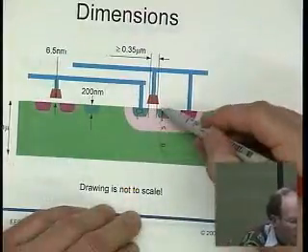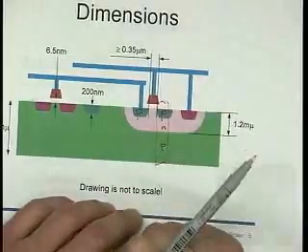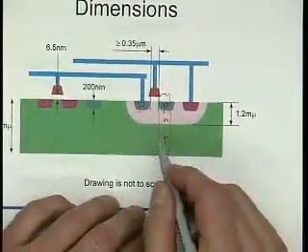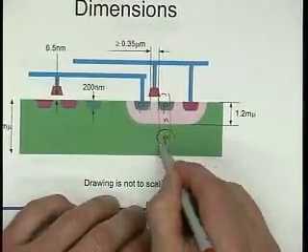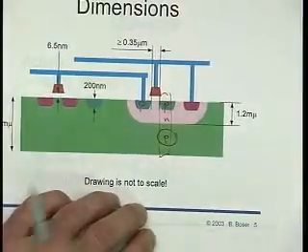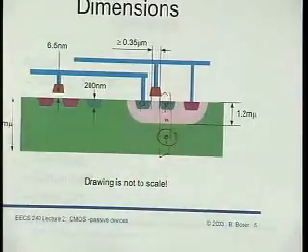This is the vertical bipolar, and there is a lateral bipolar. They both are kind of crutches. This one, obviously, problem is that one terminal is always the substrate. Well, the substrate's equal to VSS, right? And so turns out in a reference, it's not good, but we can live with it.